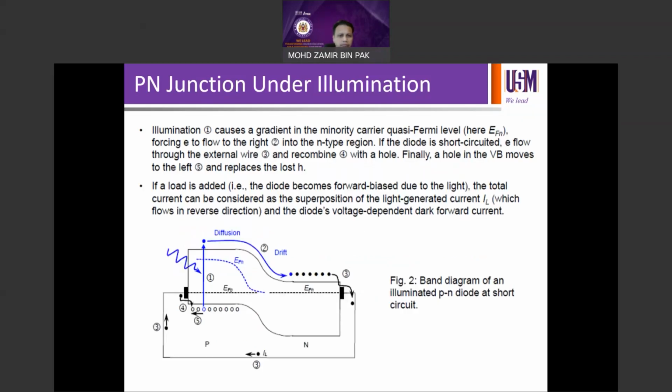So last time when we talked about the PN junction under thermal equilibrium, we learned that in order to achieve thermal equilibrium, the diffusion of carriers needs to happen from both sides of the PN junction. Assuming my left hand is p-type silicon and my right hand is n-type silicon, you have holes as majority carriers on the p side and electrons as minority carriers.